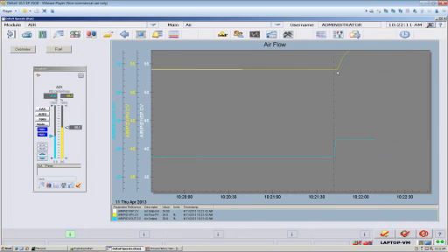I didn't see a change in my flow until right here. Again, put my mouse there and click. 10:21 and 44 seconds. I have 2 seconds of dead time. So my first piece of dynamic information, what is my dead time? I found in just a handful of seconds. Now I sized my chart right off the graph here.